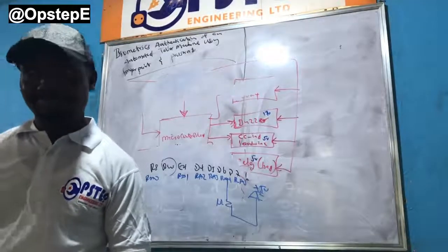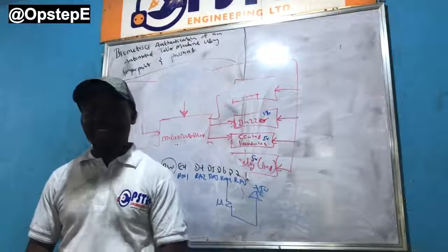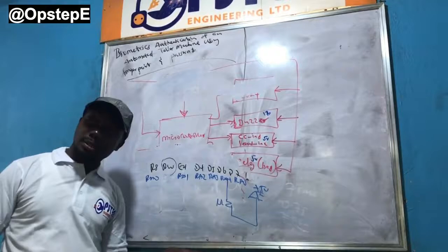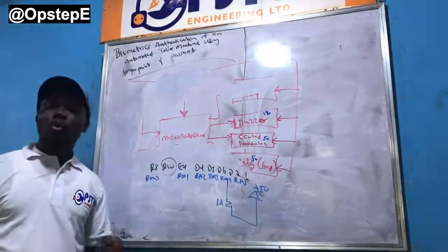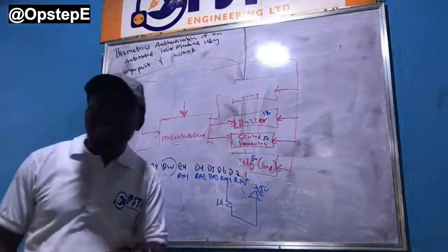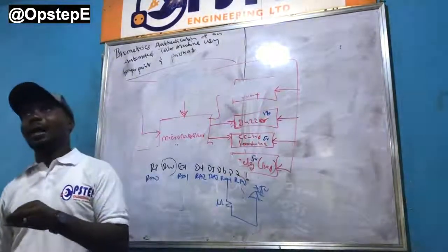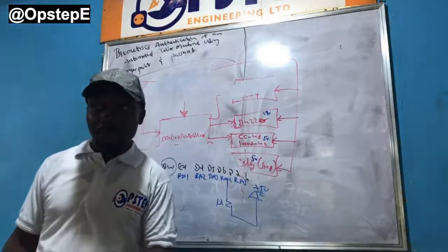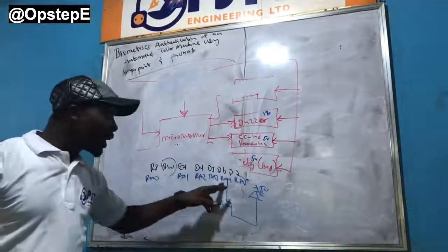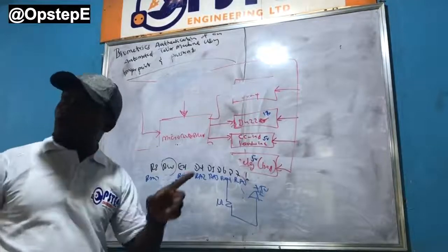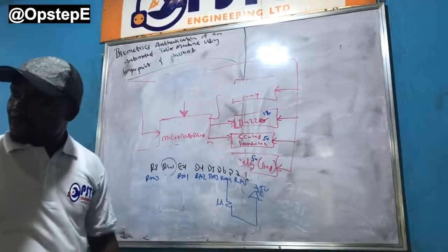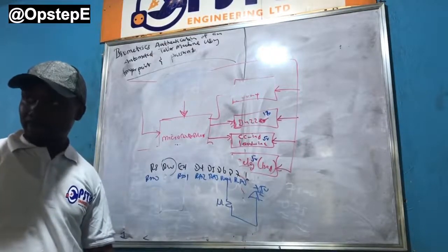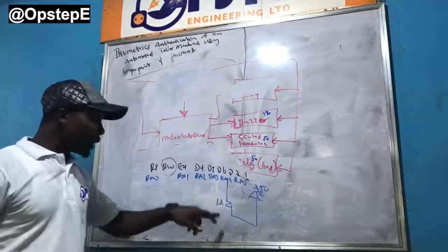Again, I'm saying this, I haven't taught you, I'm repeating it. It is important. It means you need to familiarize yourself with the states, attributes and behavior of every pin you're going to be interacting with, so you know how to actually use it. If you send a high through this RA4, of course the high will go, but you are not going to see it unless you put a pull-up resistor, because it's an open collector pin. Does it make sense?